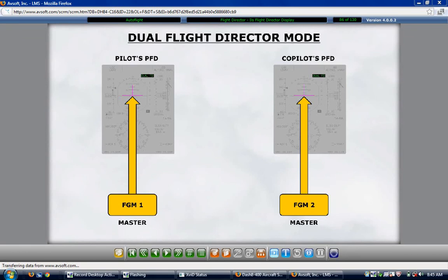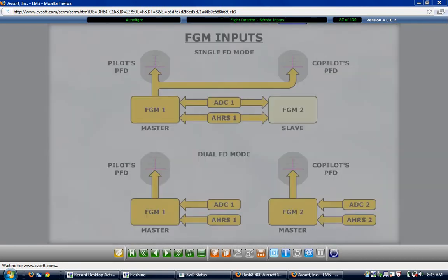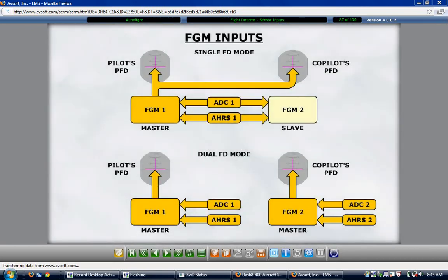If the dual flight director mode is active, both the left and right arrows on either side of the horizontal situation indicator select push button are lit, and the horizontal situation indicator select push button is inoperative. An active dual flight director mode displays green dual flight director messages on each primary flight display.